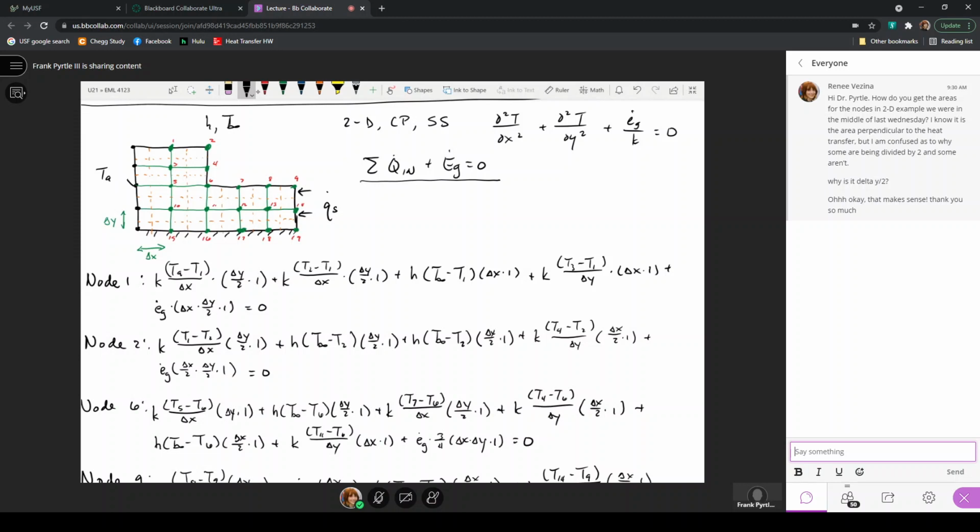The temperature at node 14 is going to be quite high. At node 9, because we're receiving a flux and there's heat transfer out of the system, node 9 would have a lower temperature than 14, and 14 would have a lower temperature than 19, but the relative temperatures are going to be dependent on the actual values.